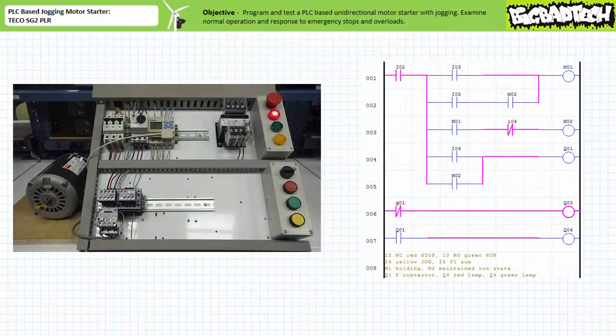When the program is downloaded to the target device and placed into operation, we can observe its behavior and simultaneously monitor the program using a live communications link. Note the two videos are synced up, however there's a noticeable lag in the monitoring utility. As can be expected, when the system is in the deactivated state, the F contactor coil is not energized, the F primary contacts are open, and the motor is off. Output Q1 is not asserted, the red pilot lamp is on, and the green pilot lamp is off.